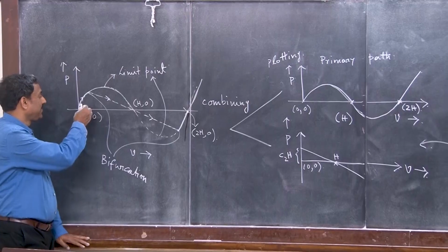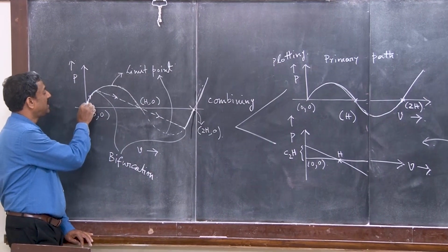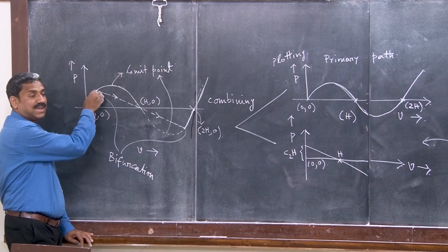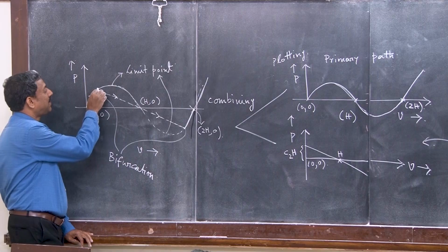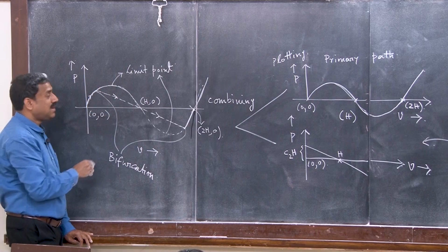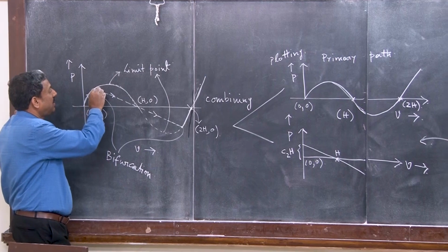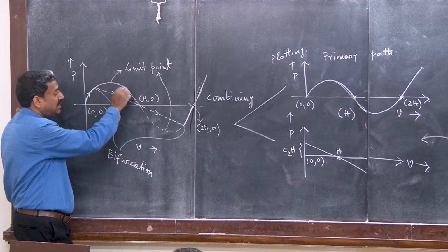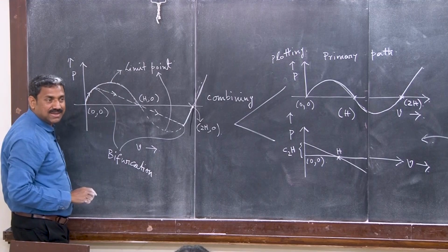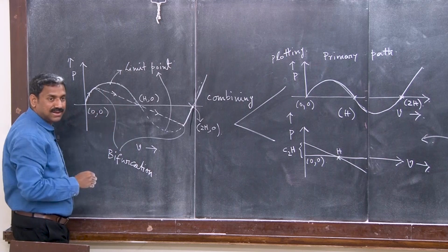You see, both. So, if I am loading the system by displacement, I am going like this. Okay. If I go by load, from here you see that this path is bifurcating into two. One is following and reaching a limit point, because this is the maximum load, the point where it is attaining maximum load. So, until this it is stable, right, then it becomes unstable, right.